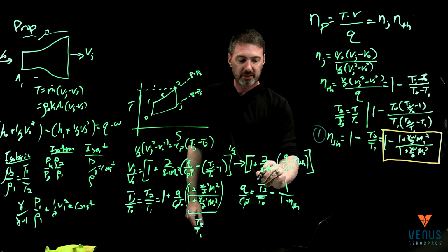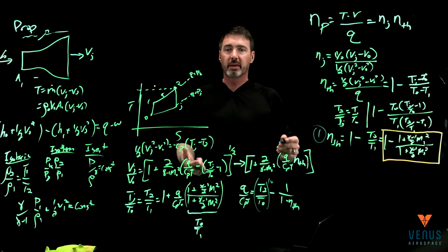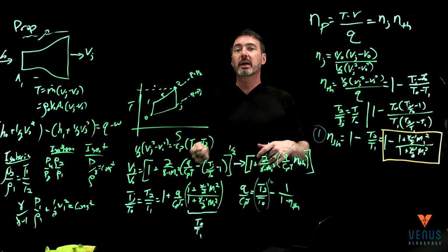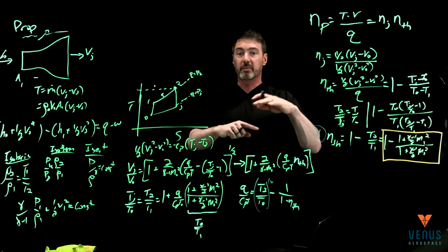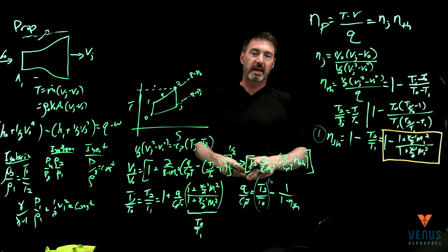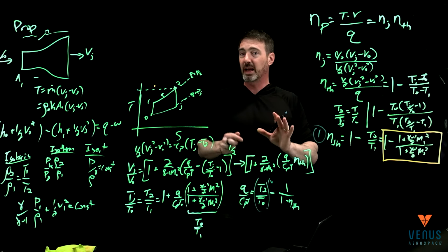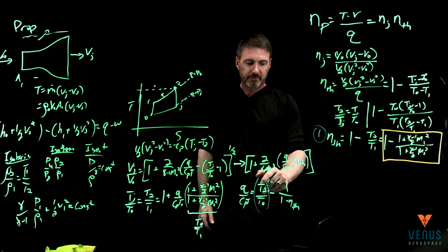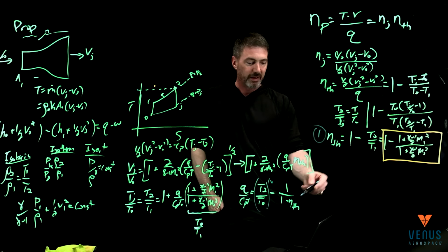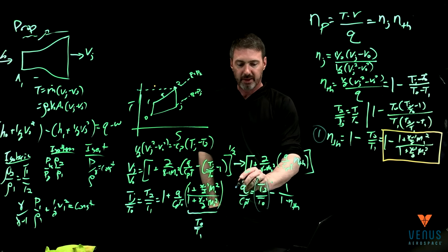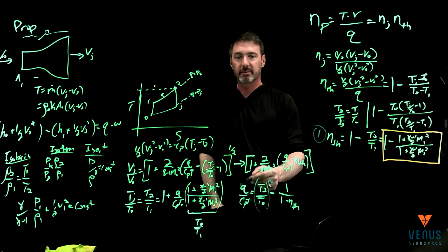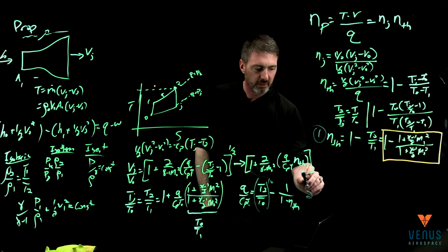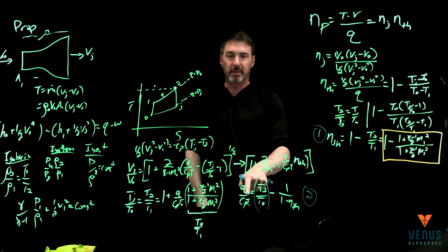Well, a good choice of this is, say, 10. At high altitudes, the air might be minus 40, minus 50, doesn't really matter. 10 times that, from an absolute scale, puts the temperatures at about 3,500 Fahrenheit. So that's probably kind of the material limit you would want to have within a ram combustor. And so if you set that to 10, I just found my thermal efficiency, I can now get how much heat I'm adding, normalized by T0. So this is sort of step 2. I can solve for how much heat I'm adding in.